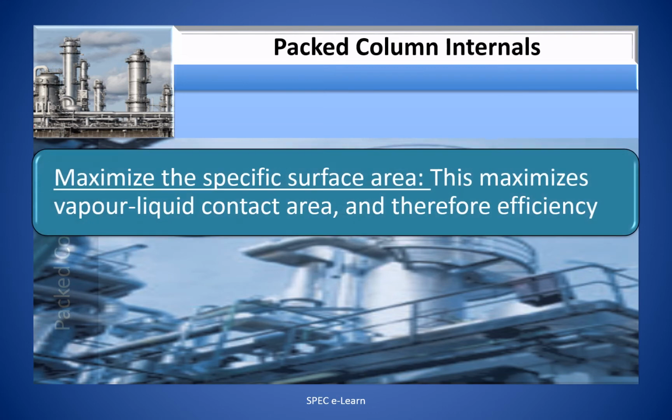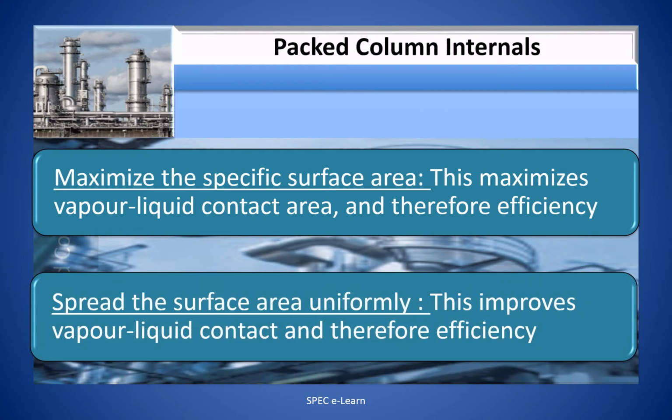Maximize the specific surface area. This maximizes vapor-liquid contact area and therefore the efficiency. Spread the surface area uniformly. This aspect improves the vapor-liquid contact and therefore efficiency.